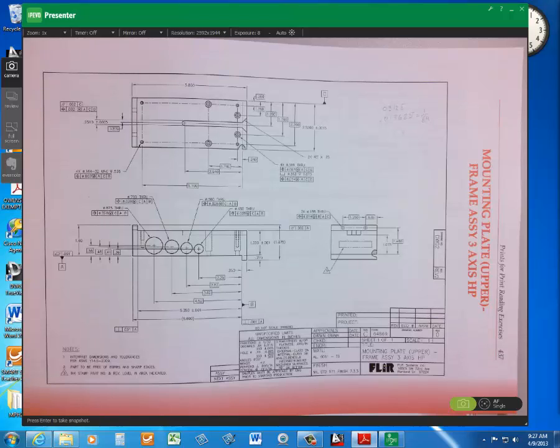So, your produced size, the actual part comes out of the milling machine, and some production person has got to check those. They'll either do it a piece at a time, or they'll have some kind of functional gauge that they'll just lay this part down on, and pins, dowel pins, or other types of precision manufactured rods could be inserted and immediately know if it's in position, immediately know what size it is.